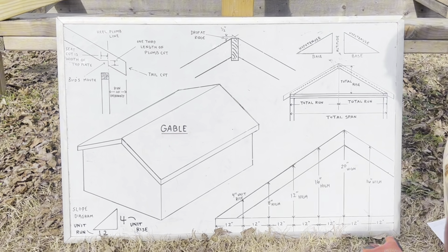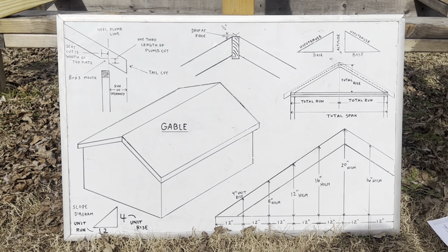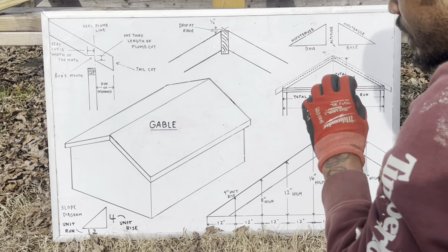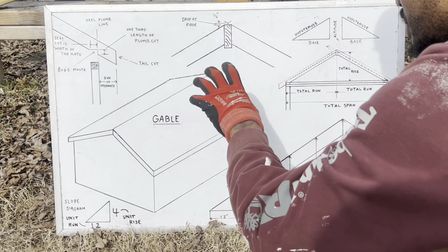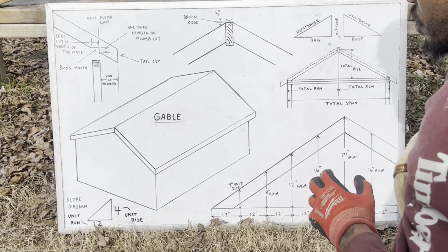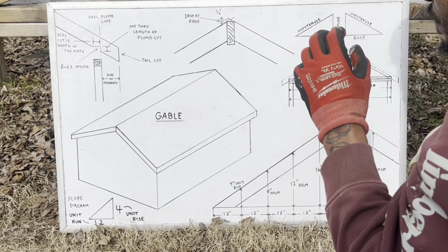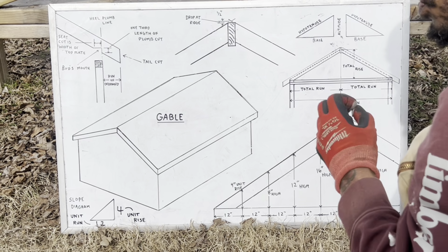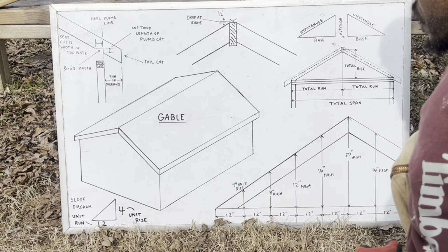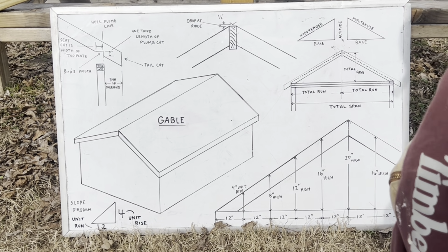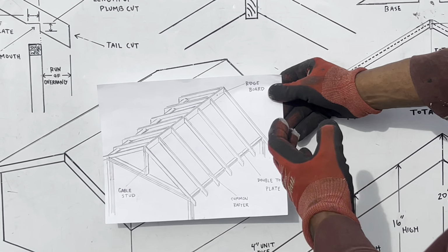which you see right here, which has 2 sloping sides, 1, 2, and your hip roof has 4 sloping sides. Now imagine that we have shingles on our gable roof right here. So we snatch that off. Up on our shingles is felt paper or underlayment. Now we snatch that off. We should come to our roof decking, whether it's OSB or plywood. Now we snatch that out. Then we come to our roof's framing, and that's what you see here.